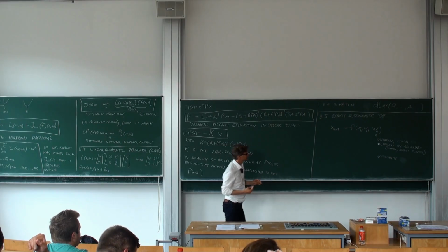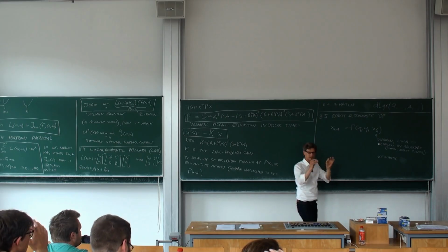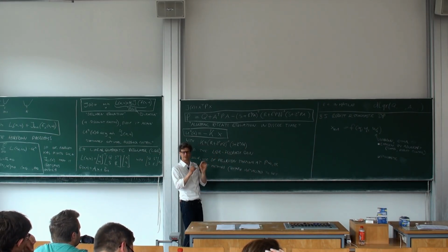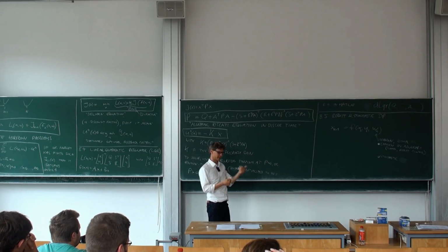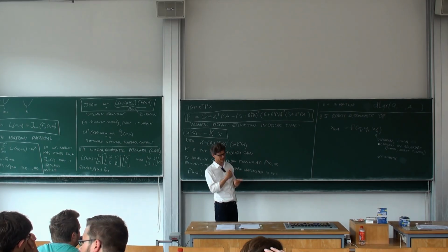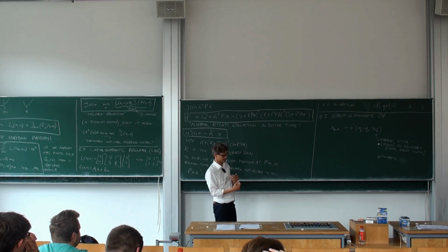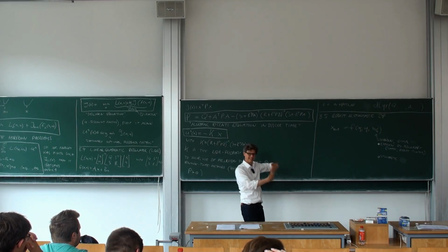In the case that these adversary actions would be from a finite set, I could still formulate it in form of scenario trees, so that is one way. If disturbance A occurred, then I do plan A, and if disturbance B occurred, I do plan B, right? That's what you could do. You could make 2 plans after the first time step, and then you make 4 plans after the second, and 8 plans, and then 16 plans, and so on.